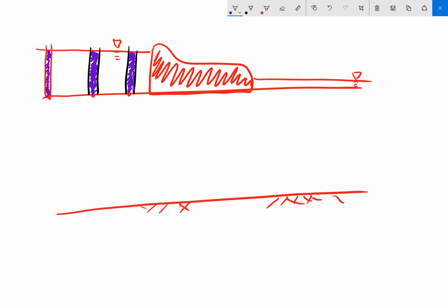My point being that any one of these points on this ground surface here have the same total head. Therefore, by definition, I could connect them with a line, and that would be one equipotential line. So the ground surface, or my boundary condition, is one of my equipotential lines. So I need to respect that.